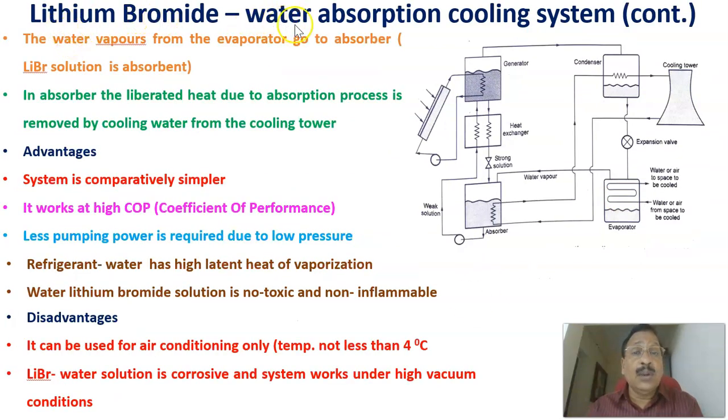Continuing the lithium bromide water absorption cooling system, the water vapor from the evaporator, after producing the cooling around the evaporator, goes to the absorber. In this case, the lithium bromide solution is the absorbent.